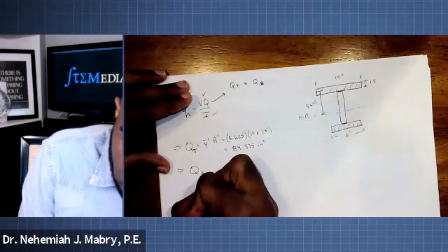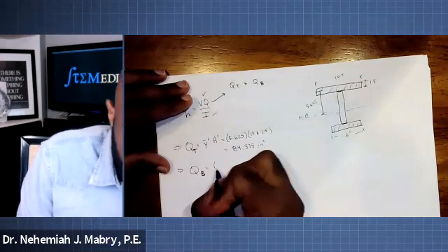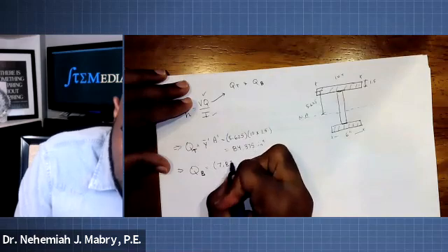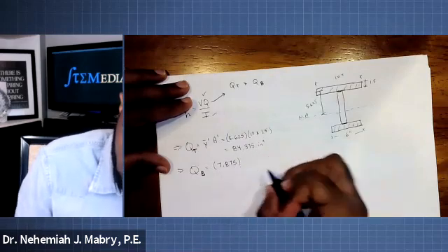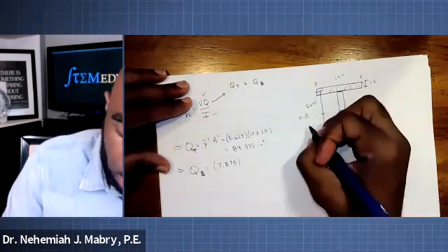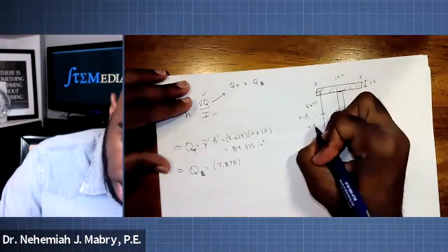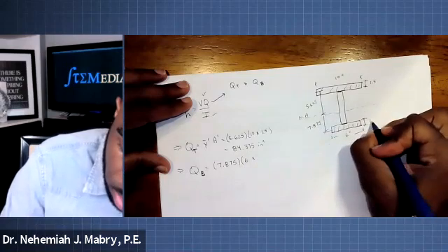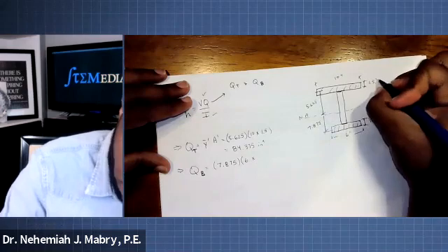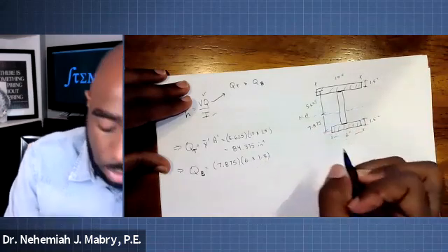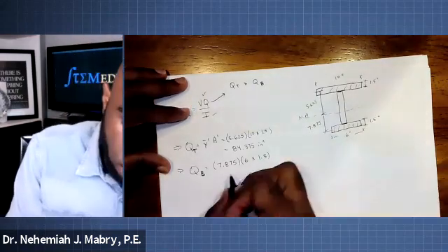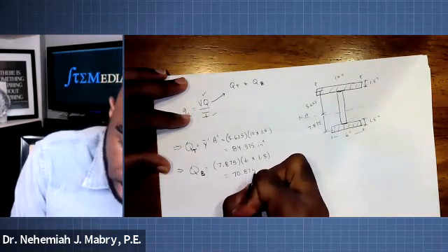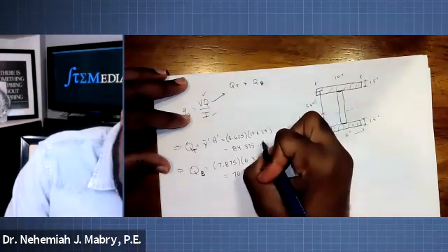Q at the bottom. That would be 7.875. You do the math of that. It's not drawn to scale here, but you will find that that y bar is, again, 7.875 times 6 times the height of this, which is 1.5 inches. And that will give you a value of 70.875 inches to the third. I'm sorry, to the third, not to the fourth.